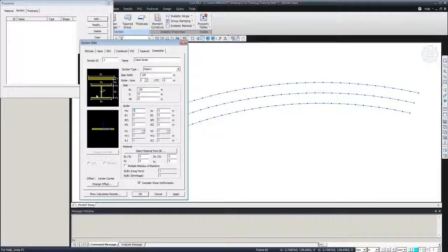So in this box, I'm defining the steel girder. Following this diagram, you can simply enter the dimensions. The total H of the web is going to be 72. The B1 will be 18 inches. TF1 will be 2.4. T-web will be 1.8, 18, and 2.4. Okay. So far, you see the section is showing up here. So this is the section I'm going to use.